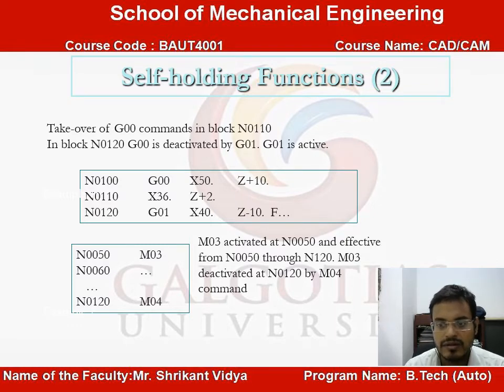So if you write M03, and after this you write M04, then M03 will be deactivated. In the same way, self-holding functions work. Two functions are interlinked, suppose a spindle off and a spindle on. If you have made the spindle on, then for making it off you have to write the next M command in the next line, the next block.